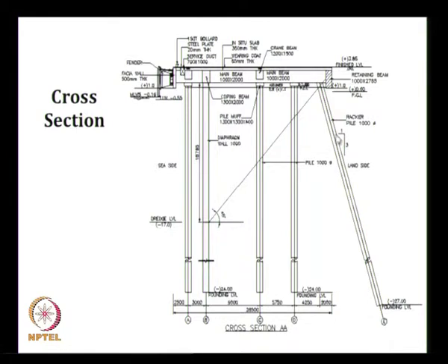The construction companies prefer a steeper one, about 1 in 4 or 1 in 5, but it is preferable to have 1 in 3, because an axial force in the member will have two components, a vertical component and a horizontal component. This horizontal component will take care of the horizontal forces. So we have three equations of equilibrium: sigma of all the vertical forces is 0, sigma of all the horizontal forces is 0, sigma of the moment is 0.